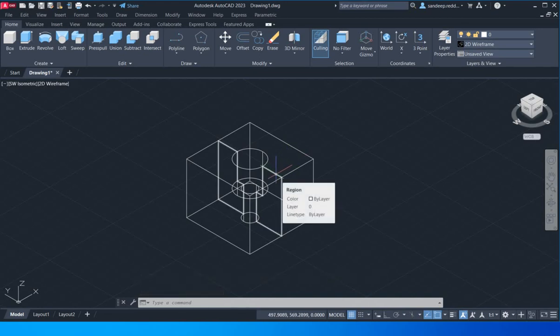It's that simple. As I said, it doesn't make any difference to your drawing. The only thing it does is add a section plane. It doesn't slice your object, that is separate to sectioning. So we have created a section plane which is parallel to the YZ plane. Now that is using the 3-point method of sectioning, which is quite straightforward.